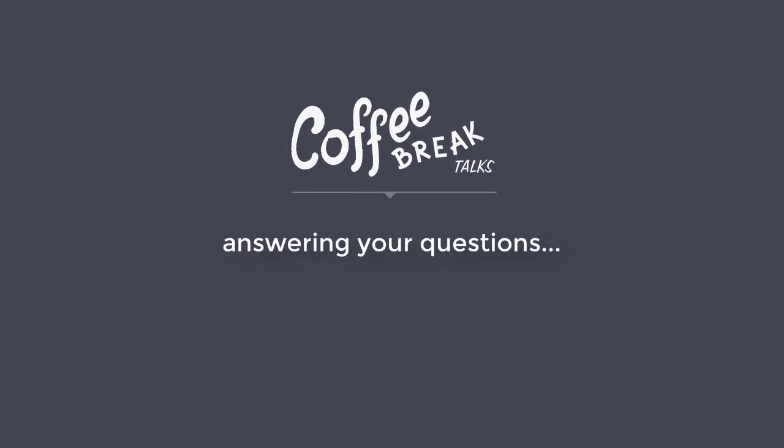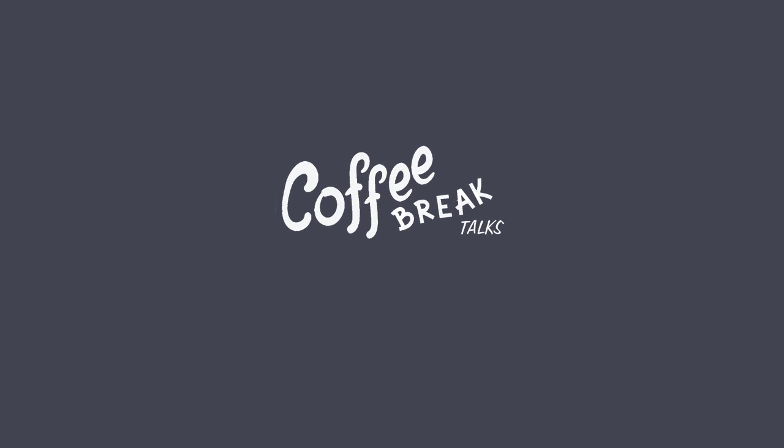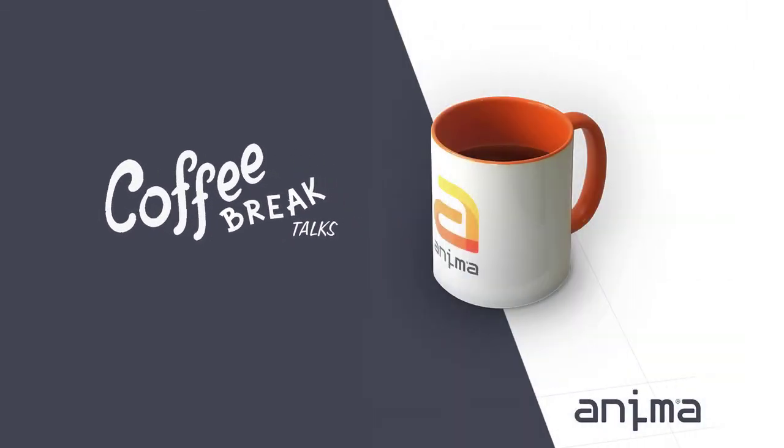We received one question that we want to answer. It is made by James, who is asking about a very big project. So James, in your case, for a project that large, I would suggest splitting the 3ds Max scene into different sectors using XREF, for example, and then making one Anima scene for each XREF. Okay, this is quite interesting.